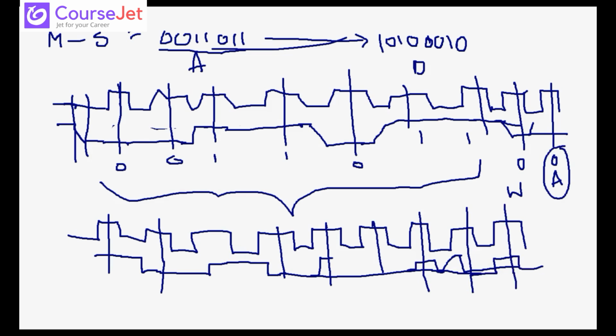So the not of acknowledgement bit has to be 1, and then give a stop signal. When my clock is high, we are giving a low to high signal, which you consider as stop. So from here to here is my stop signal. In this way we are sending your I2C data.